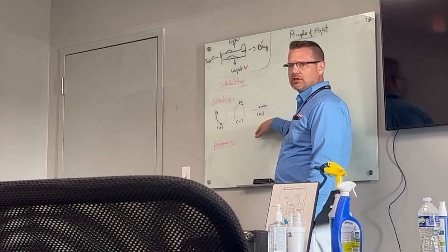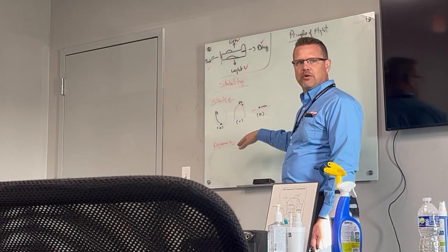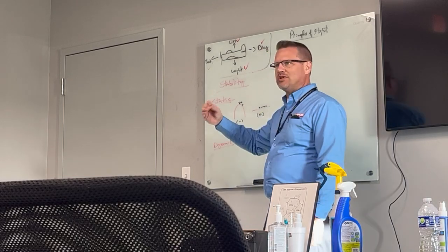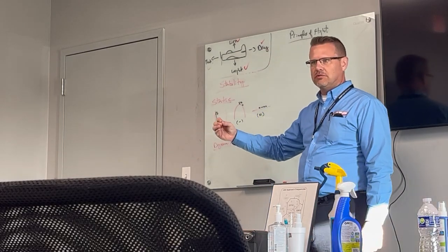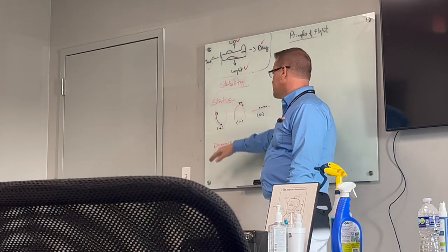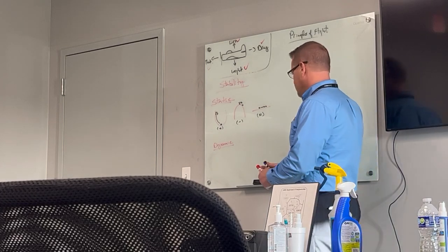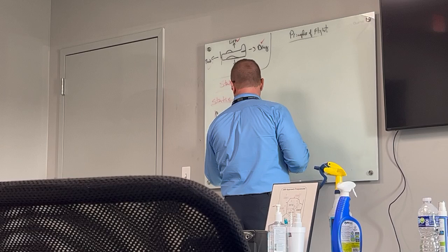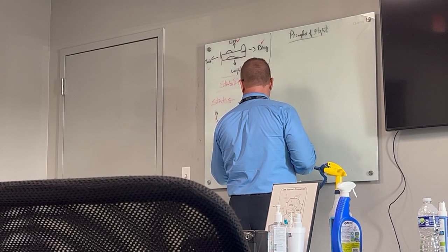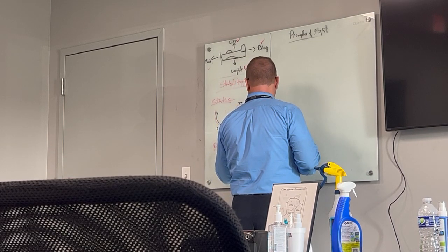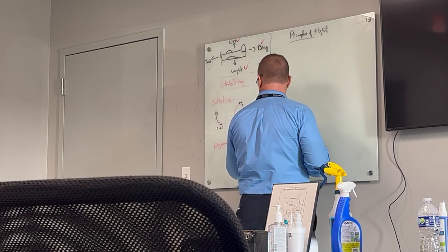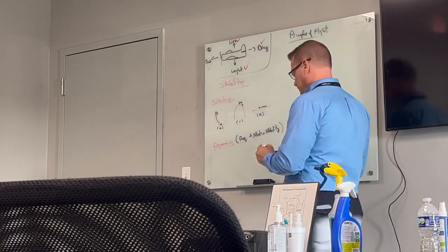Because they never return to equilibrium. The only way in which we can achieve dynamic stability is if we have something that wants to at least initially return to its state of equilibrium, and that's to have positive stability. So dynamic stability requires positive static stability. Without that, you cannot have dynamic stability.